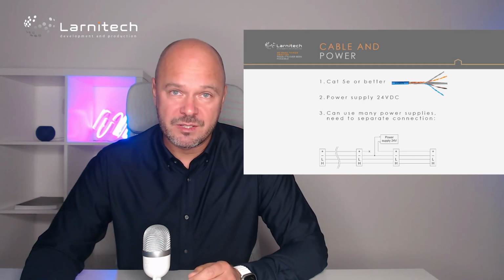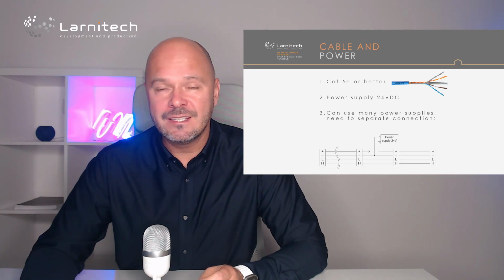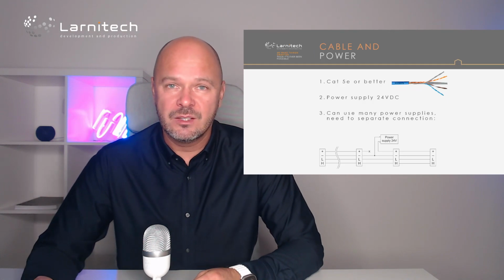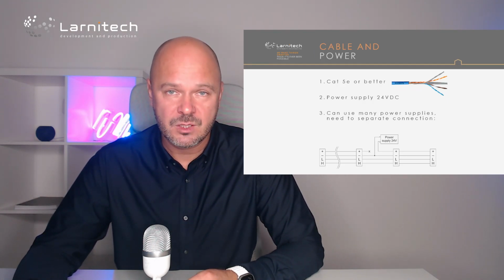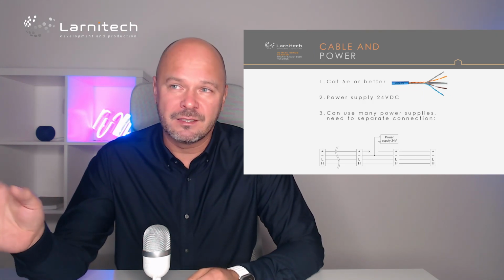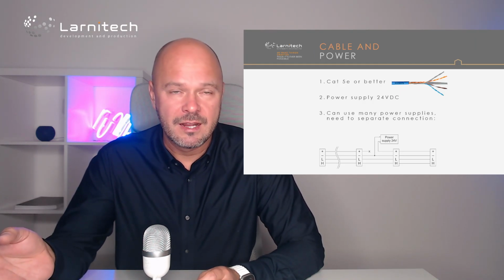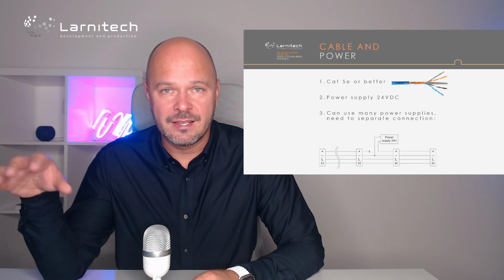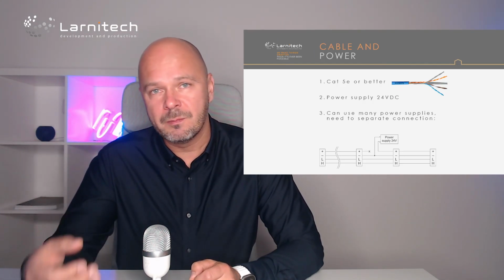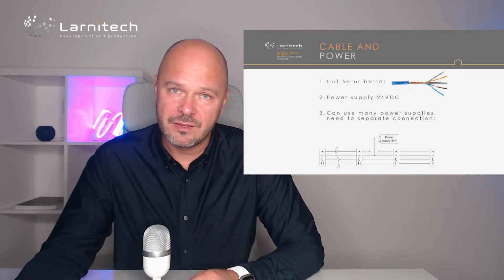Can we use many power supplies? Because sometimes we need to. Sometimes we have devices which need a lot of power, and how much power is needed you can see in the documentation. So you open the documentation and see that a device requires maybe 100 milliamps of power, and then you use many devices and your power supply is not enough. So if you need to use many power supplies, you can, but you need to separate them from each other.